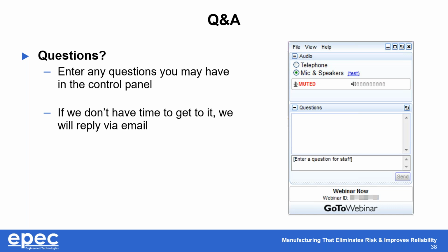Adding just a half a mil of space between those 3 mil traces makes manufacturing so much easier. Pad to hole ratios, not considering annular ring, not supplying any kind of netlist testing or netlist data to us so we can test out your data to be sure it's correct. Missing drawings, missing drill programs, just not enough information sometimes coming in the door.